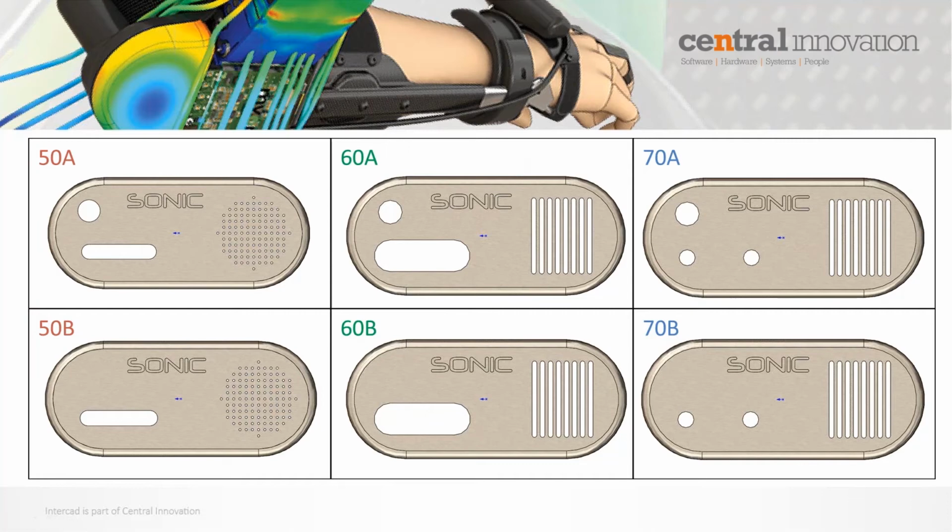So if you have a look at it, notice there are 3 main variations. These 2 designs use 2 different cutouts for a speaker, and these 2 designs have 2 different button slots available. So this uses a slot design and this uses a circular hole. And also each primary variation has a sub variation where the volume button is suppressed. That could be done as well by using something called a derived configuration. And let's see how that is done in SolidWorks.